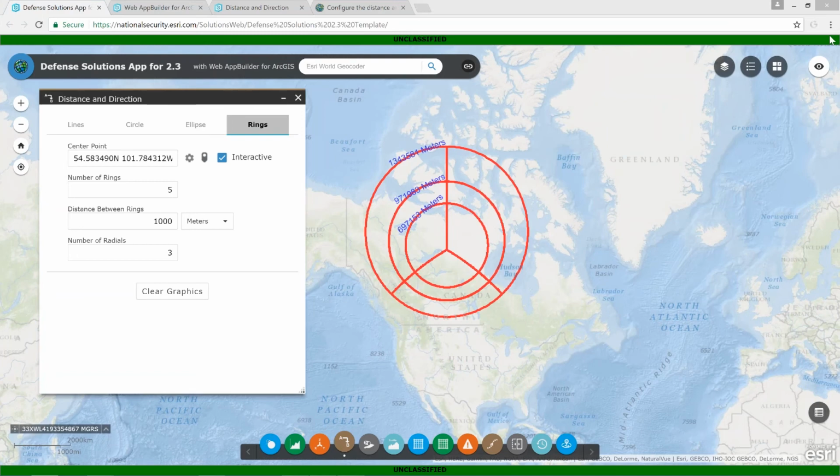What will these graphics look like in a 3D space? So in 3D, these will simply show up draped onto the terrain that you have. They'll show up as 2D features, so if you have them in a 3D scene in ArcGIS Pro or ArcGIS Earth, they're simply draped. If you're looking for range domes, we do have a template called Range Dome Analysis that's separate from military tools, but it'll enable you to create range domes in a 3D scene in ArcGIS Pro.